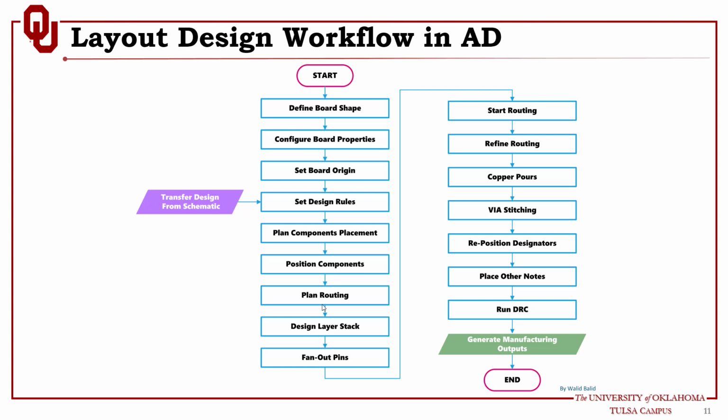They should not be separated. There should be no discontinuity in the routing. Make sure to route them all together because they have the highest priority. Then you can route the rest of the components.